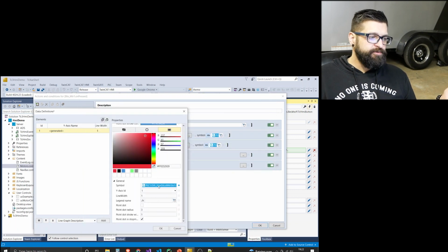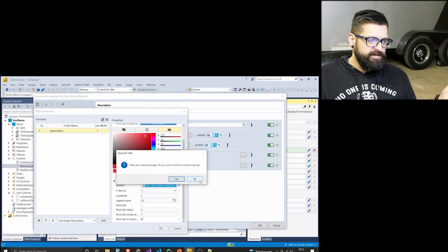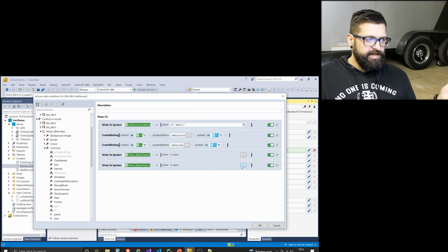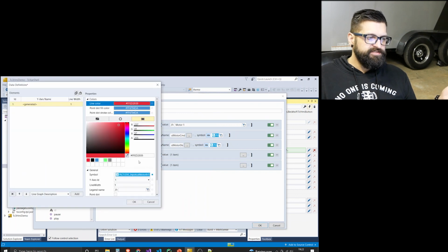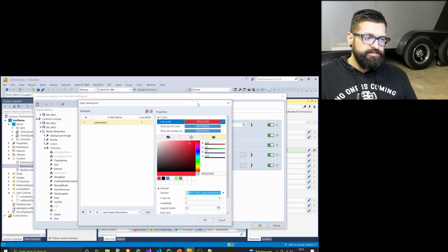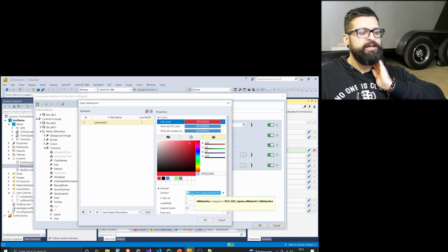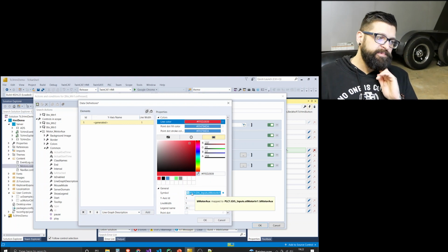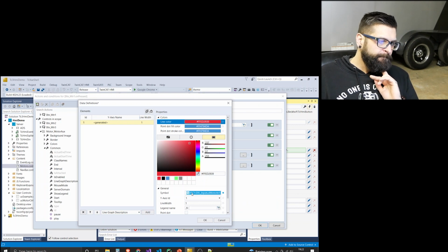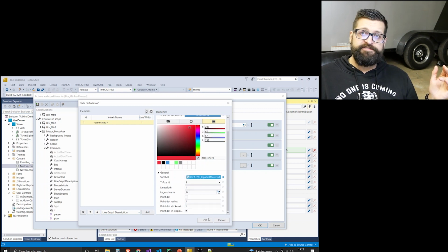It's the exact same protocol for the aux contact. I click over here on the trend line chart for my aux contact, and you can see that the symbol that I'm binding it to is my GVL inputs motor, ST motor 1 in, and it's the aux contact element of that structure. Okay, so that's how I'm dynamically passing these values around.